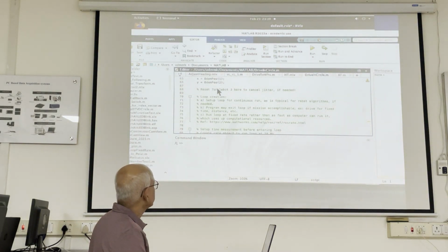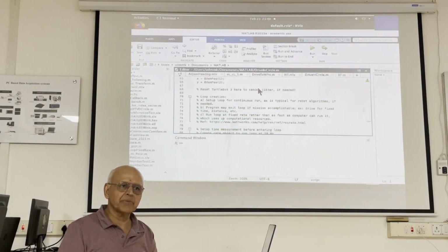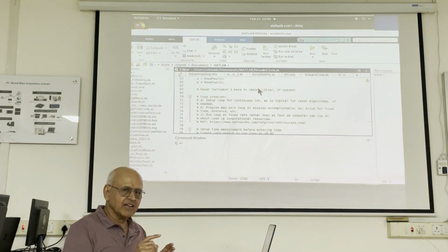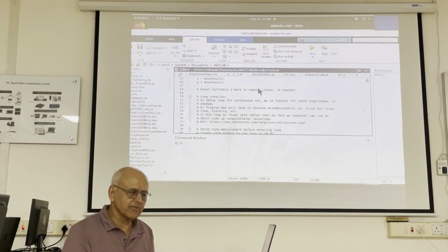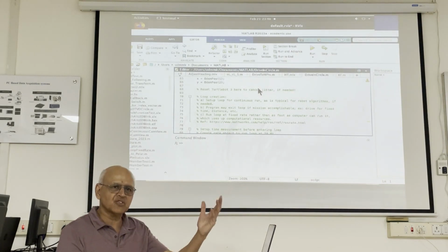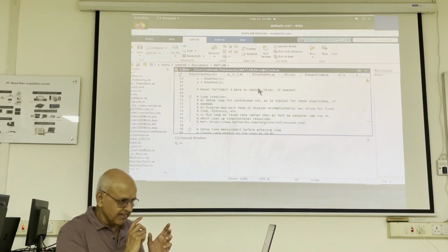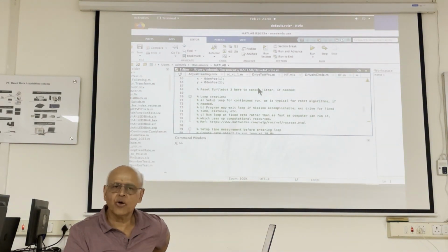We'll get to this later. This program doesn't have it, but maybe I'll tell you what it is even though we haven't addressed it. So you'll notice the TurtleBot 3, even when it is stopped, it starts to move slowly and it will swing all the way around. It sometimes happens, sometimes doesn't. You know, sometimes you go for a cup of coffee and you come back and you just launched the empty world and the robot is facing in a different direction. In other cases, if you watch it, you can actually watch it turning around. So I call it jitter. So it's a known problem.